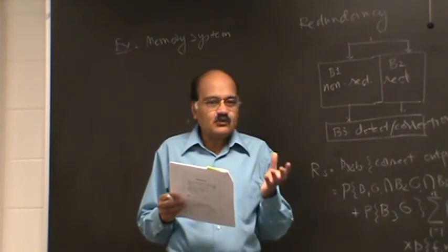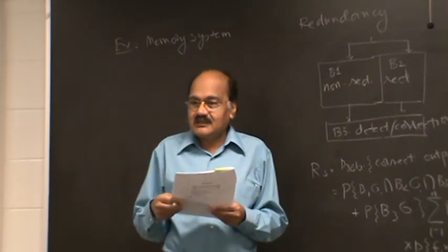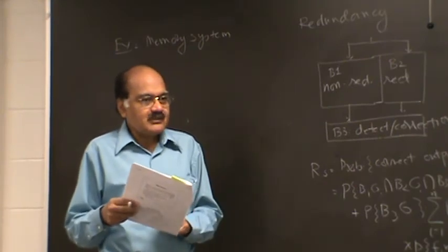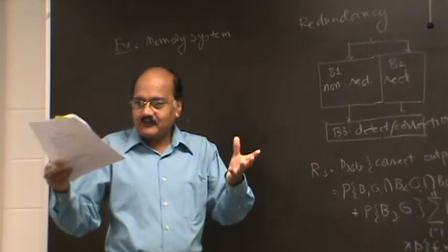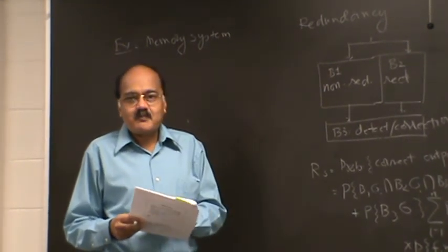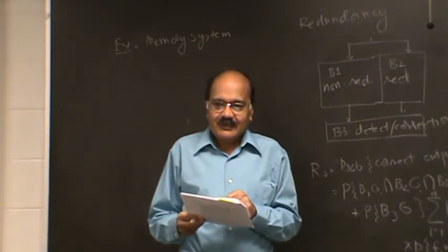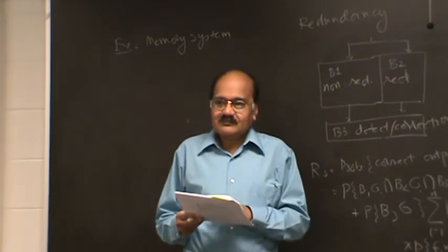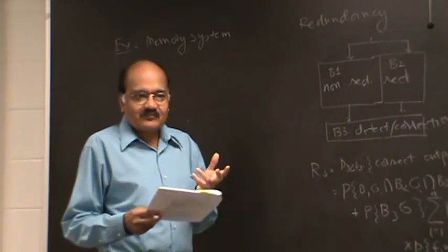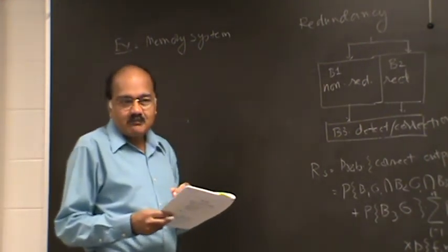There's almost nothing you can do that will eliminate them. So they're a bigger problem probably in space where there are more charged particles, but even in normal atmosphere, you always have charged particles coming out of everything. So this piece of paper, there's some charged particles coming out of here all the time. And the material that encapsulates the IC chip, that is releasing charged particles. So people have found that because of the smaller dimensions, it has again become a significant problem.